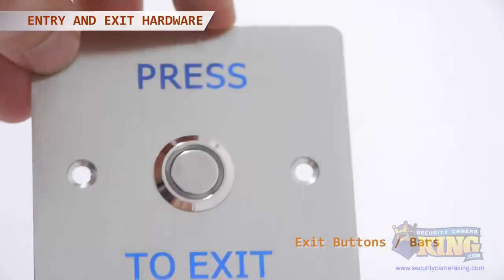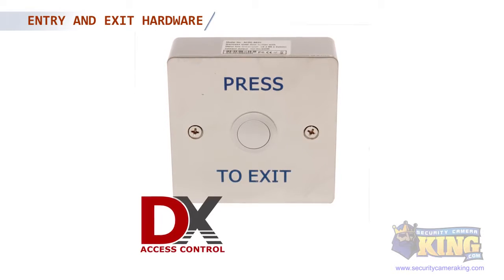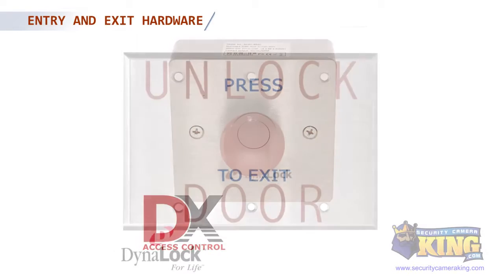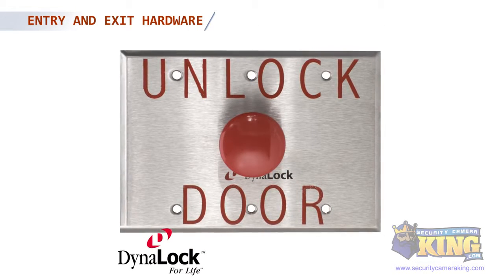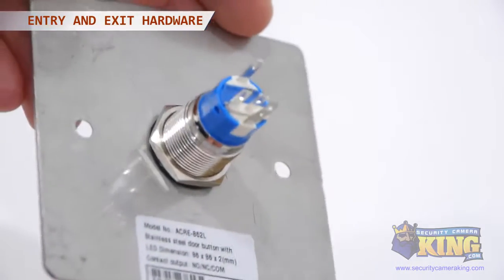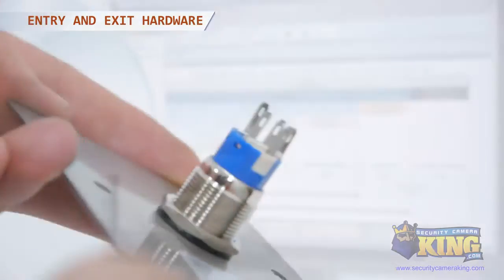Exit buttons and bars usually go on the other side of a door and allow a user to request to exit from a secured area. There are a variety of exit buttons and bars. Some are simple electric-powered buttons, and some are pneumatic. Pneumatic buttons do not rely on power, so an exit is possible even when power isn't available. There are also exit buttons with a delay for more secure areas, where the user must wait a few seconds before an exit is possible.